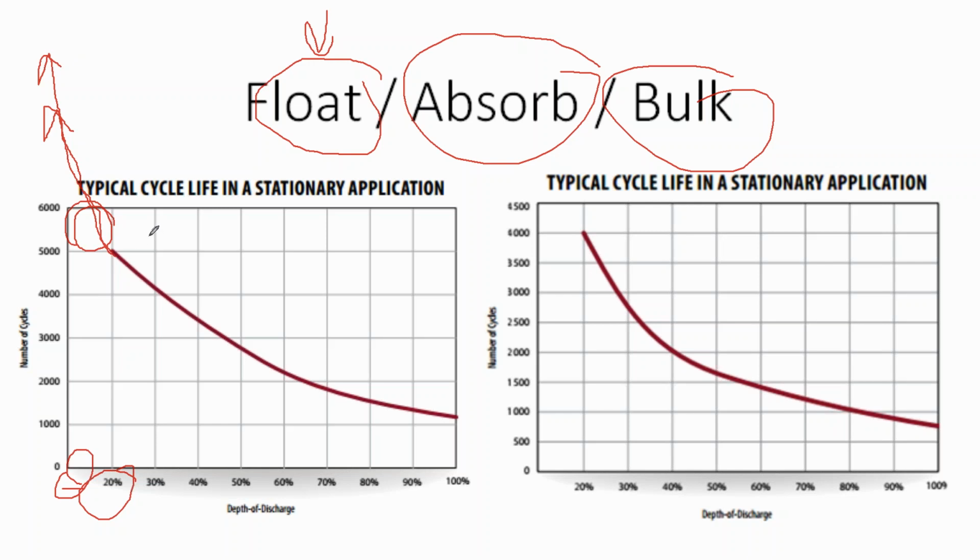Actually, for conditioning and maintenance, when you pummel the battery with energy, that helps bust some of the barnacles that cover the plates of the batteries off. And it's that plating of the battery that reduces its life. And so during your maintenance cycles, you're overcharging the batteries at high voltage to maintain them.